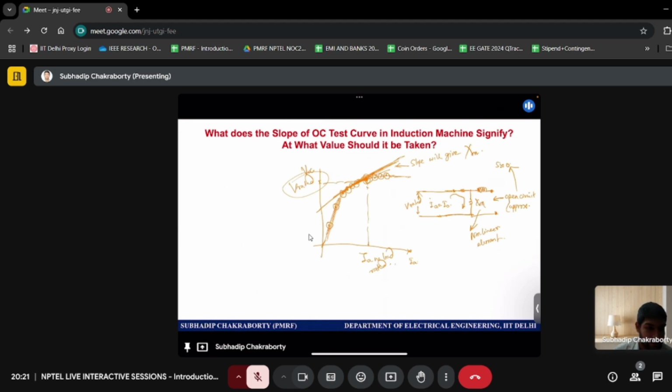We can use self build up of voltage if we can provide external excitation or reactive power from passives like capacitor banks. That capacitor bank should be able to compensate for this XM so that we can supply the required amount of reactive power at the rated voltage, right? For that, we calculate XM so that we can compensate it using other passives for standalone operation.